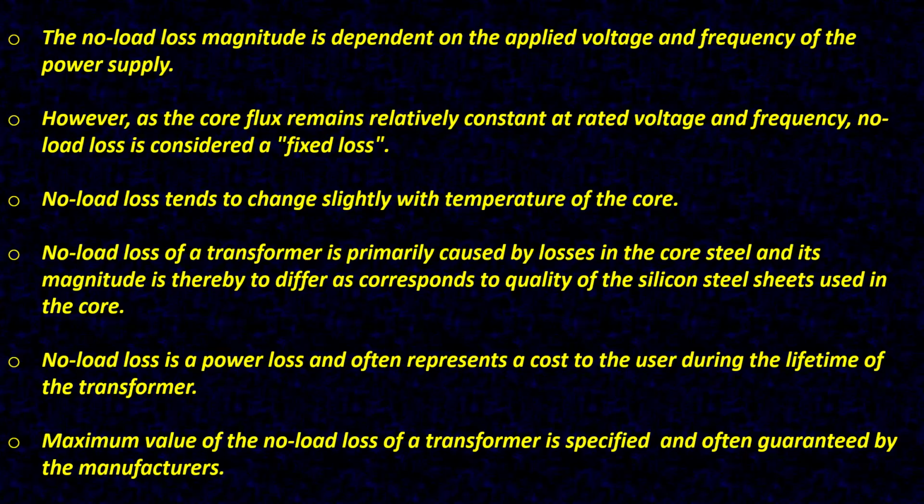No load loss of a transformer is primarily caused by losses in the core steel, and its magnitude differs according to the quality of the silicon steel sheets used in the core.